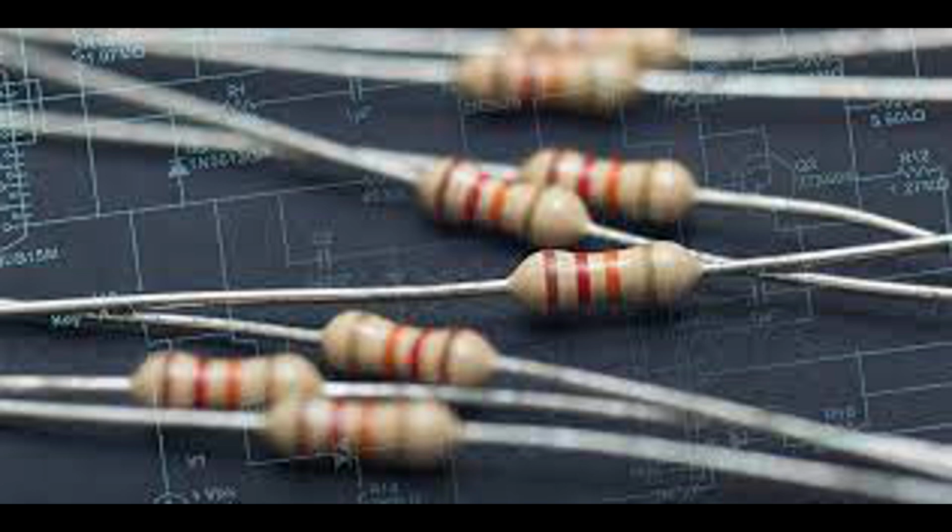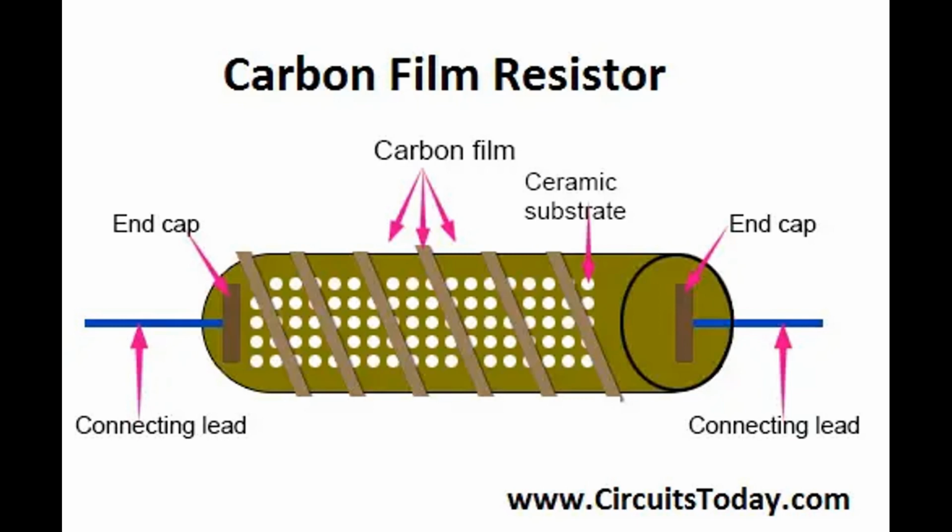Filtering and signal processing: in some cases, noise can be filtered or mitigated using analog or digital signal processing techniques. Filters, such as low-pass filters, can be used to reduce noise at certain frequencies, and digital algorithms can be employed to process and clean noisy signals. Trade-offs: reducing noise often involves trade-offs with other resistor characteristics, such as temperature coefficient, cost, and power handling capabilities. Engineers must carefully balance these factors based on the requirements of the specific application.